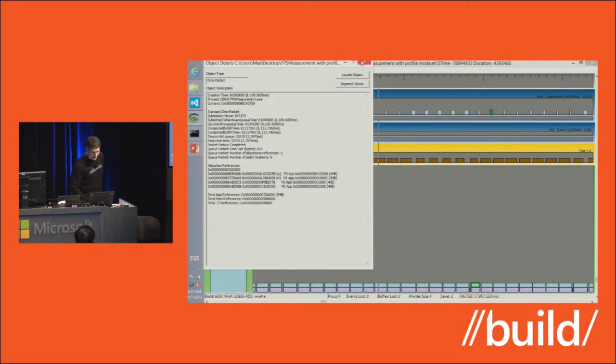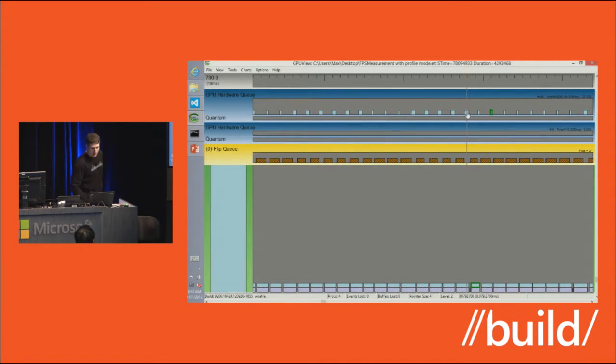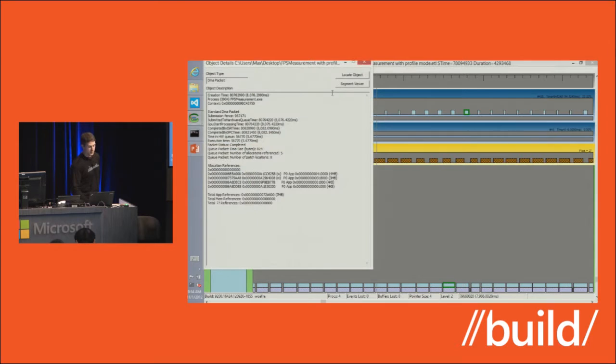But what we also get insight into in the GPU view is that when we're running in this slower 60 hertz mode, these platforms work extremely hard to optimize battery life and power. They dynamically change their clock rate at a very high frequency. And the GPU workload for this app is relatively low, so they can decrease the clock rate and still get a frame out in 60 hertz. So running at slower clock rates, it's actually getting 5.6 milliseconds instead of the 2.6 we saw earlier.